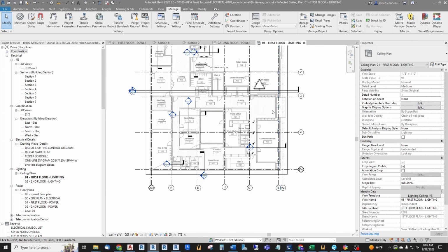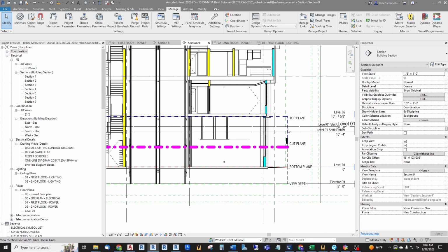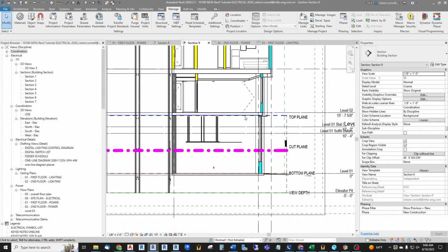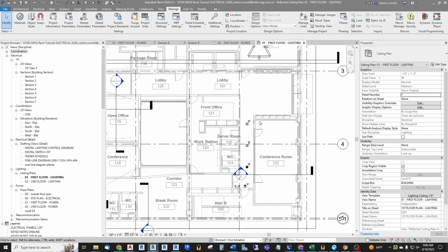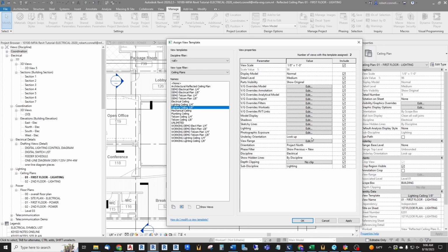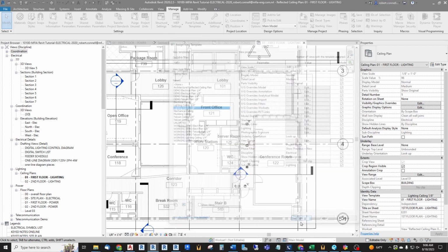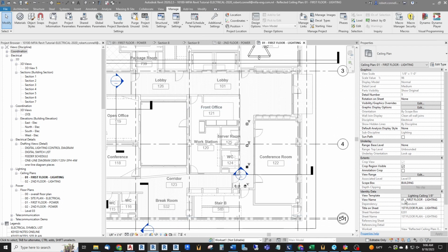This is our lighting plan, which is based upon a ceiling plan, as you see over here. So it is similar to this, but it's looking up at the ceiling, and it's reflected like off the floor, but it's like we're looking up. So it behaves a little differently. Let me pull the view range out of this template again, like I did for the floor plan, to experiment. So I'm unlinking this view range from the view template. Now I can play with the view range.